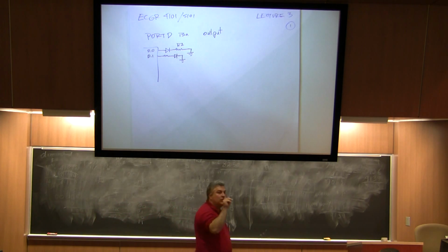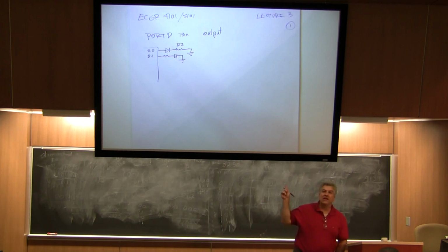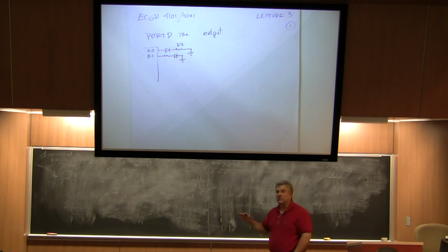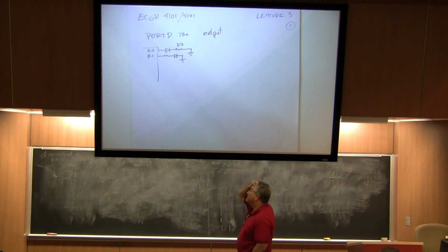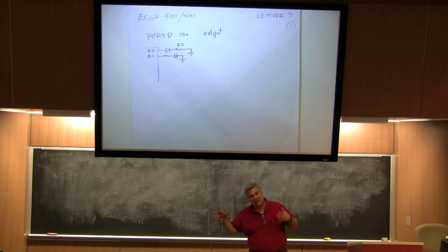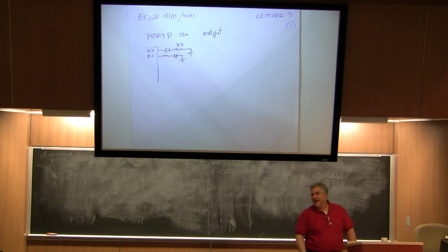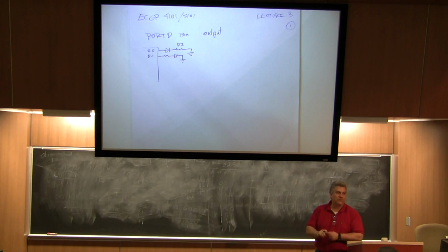Well, one thing to mention too about the output pin of a microcontroller, how much current does it source? It depends on the microcontroller. Usually it's really low. Something like 5 milliamps is not unusual. So from this respect, does it usually make a difference? You know what? I've asked this question to people who design these, and I've got both answers, believe it or not.